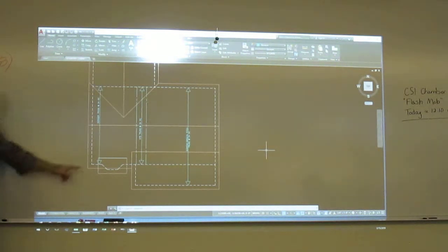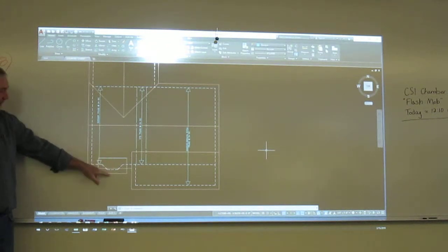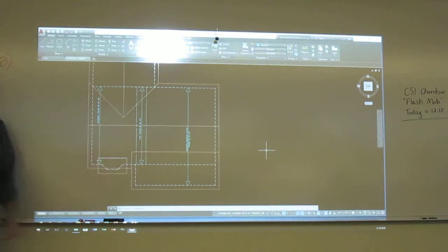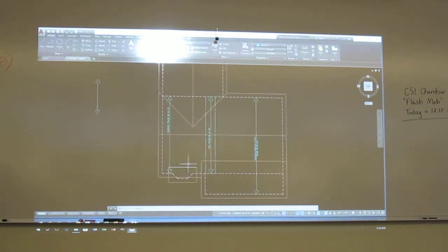and it'll look like it's part of it. On this one, I'm going to hand stack it. By that, I'm going to have my framers build it, because all it is a couple 2x6s. When you do not know how a roof is going to bear, and you're going to have them hand stack it, what you do on your note is you stop your arrows short of your bearing, or you do not terminate them on bearing. And that's a kind of a convention we've got saying, you're hand stacking this guy. Okay? By hand stack, I mean building on site.